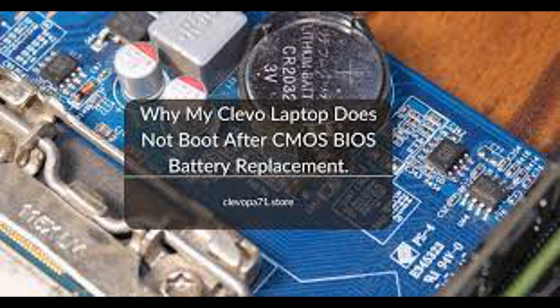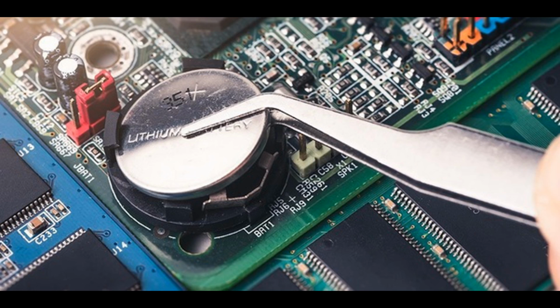During switching, both NMOS and PMOS transistors momentarily conduct, creating a path between the power supply and ground. However, this path exists only momentarily during the switching transition, resulting in minimal power consumption over time. Additionally, CMOS technology allows for rapid switching transitions, minimizing the duration of power consumption during switching events.